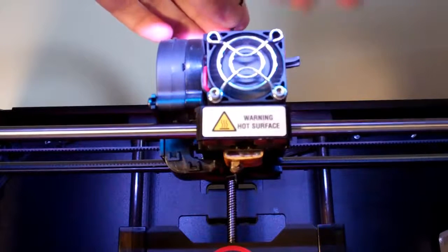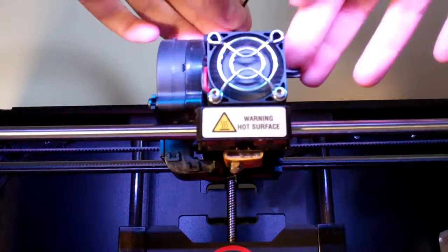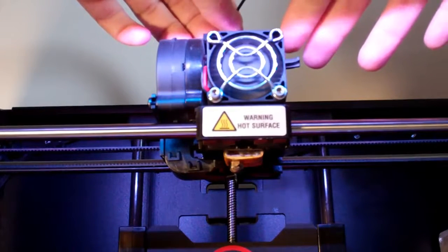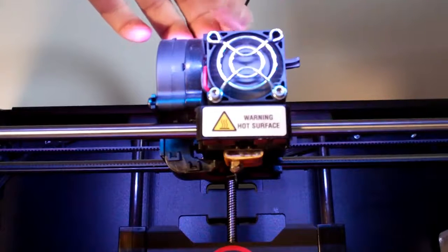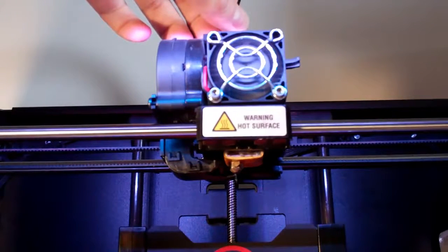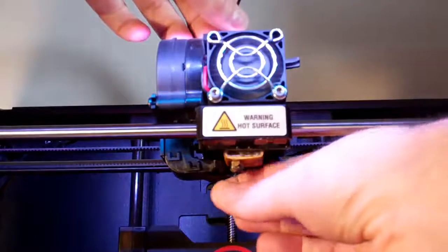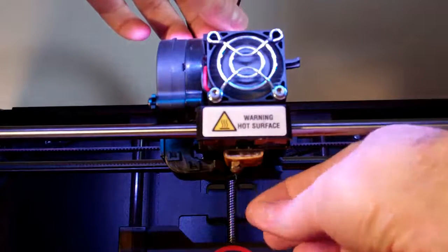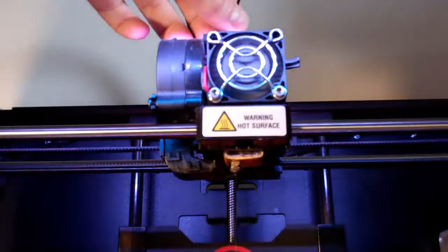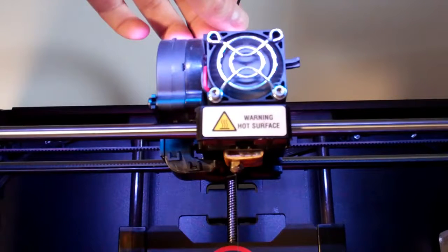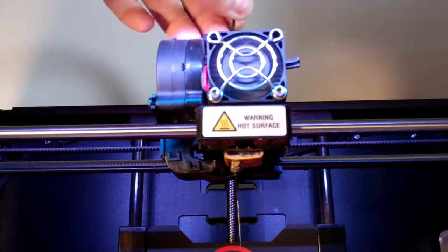Press the little lever down to allow it to go in. And let it feed through, and you'll see it extruding out of the nozzle in a second. It'll take a while just to feed through because we pulled a lot of it out last time, out of the extruder and the nozzle and the hot end. So you can just see that extruding now. Give it a little helping hand, and yes, I do burn my fingers doing this, and I wouldn't recommend you put your fingers near the hot end, even though I do it myself.